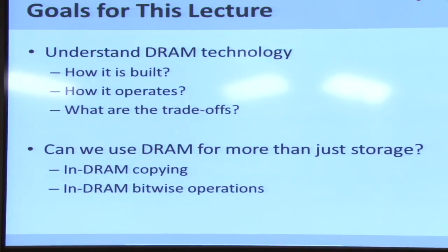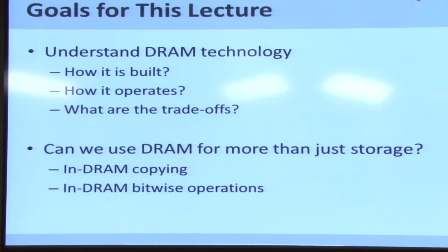I was actually surprised that initially we used to have an abstraction for a DRAM bank, which is you read a row of data, and the precharge command writes back the data to the DRAM cells. It's nothing of the sort. So it was in some sense very liberating to know how DRAM operation was so simple.